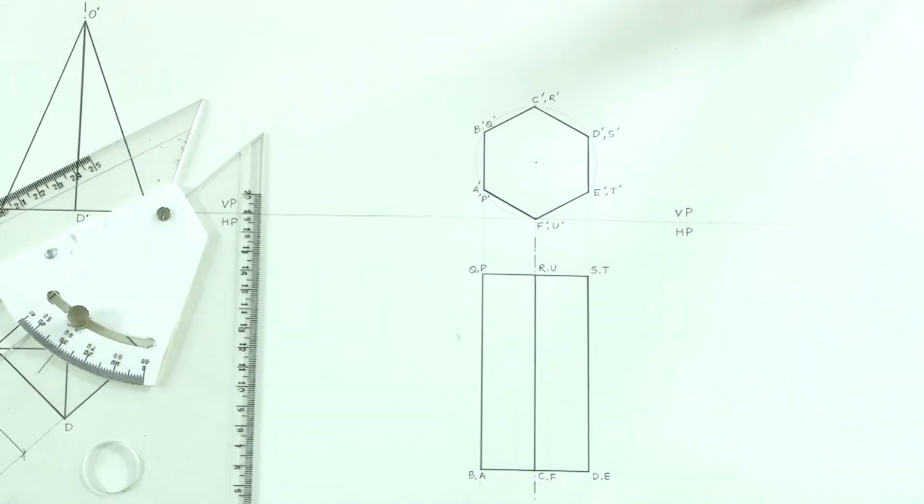Just imagine where you are going to see the parallel faces. So in case the parallel face is going to be seen in HP, you will start drawing from HP. In case the parallel face is being seen in the VP, you will start drawing in the VP. That's a simple rule because that is how you will be able to draw the true sides, the true sizes and the true shapes of the solids.